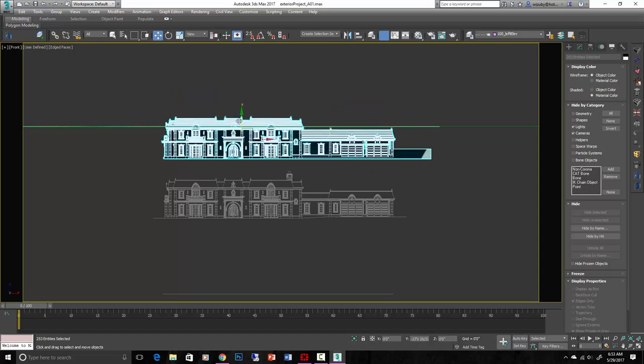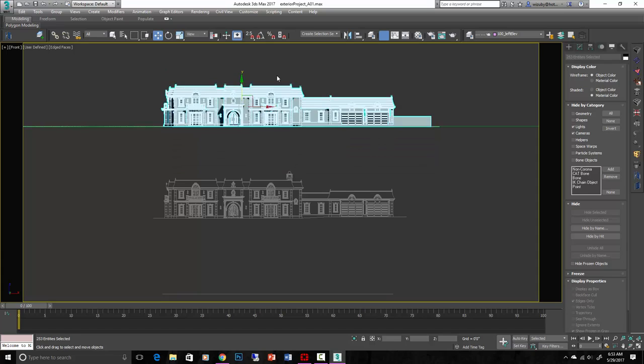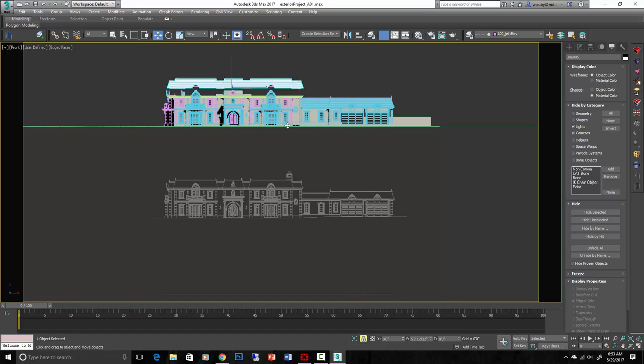If you do want to use gizmos, it's totally okay. I don't use gizmos. I just select things, lock the selection by hitting spacebar as a hotkey or hitting this lock down here. And then with gizmo off, I can just move it in the Y or use a hotkey to move it in the X only, like so. I've showed all this before.